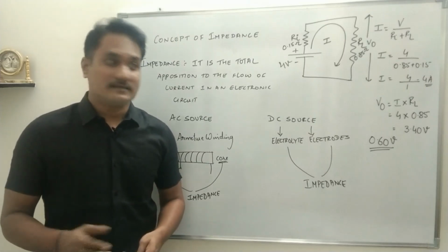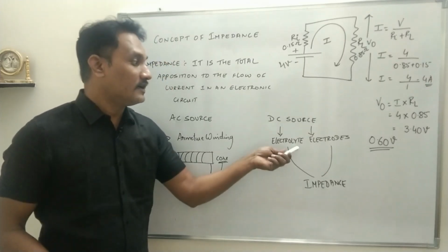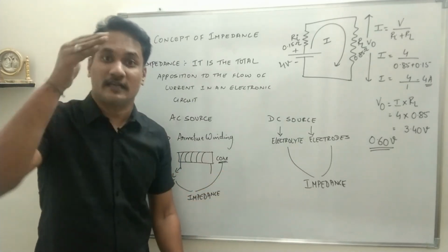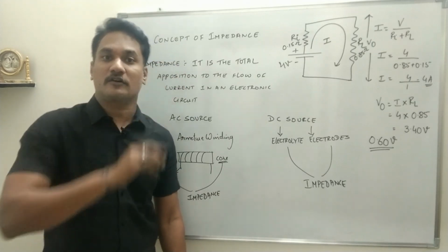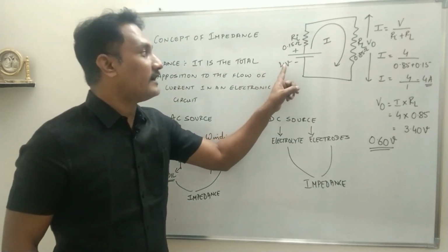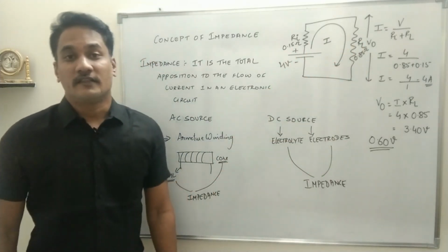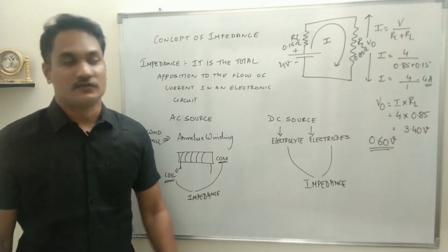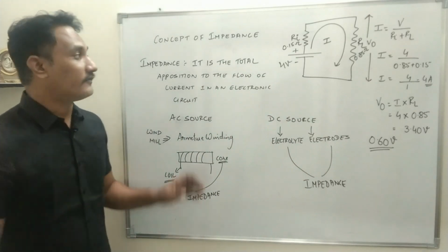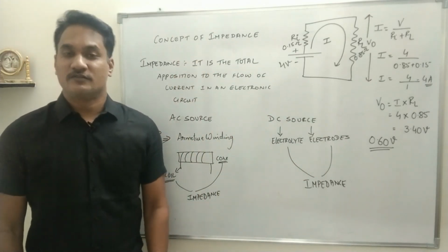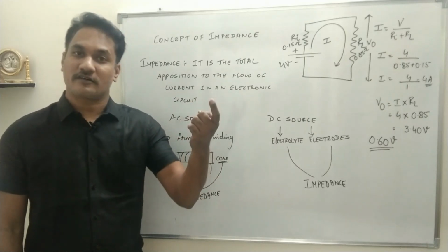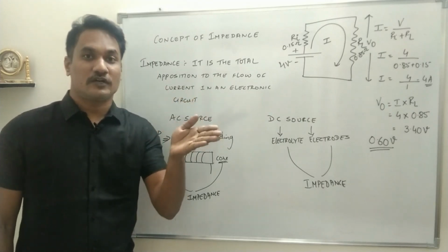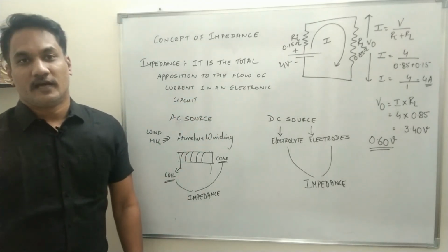So what is Ri? Ri is nothing but the impedance. Impedance is the resistance offered because of the components used to design the source. That means every source will have impedance. If the impedance is there, some voltage will be dropped across the impedance, and you will never get the entire voltage at the output. So this is the disadvantage of having impedance, and this is the objective of understanding the concept of impedance. If there is impedance, some voltage will be dropped across that impedance, and you cannot get the entire source voltage as the output voltage. I hope you have understood.